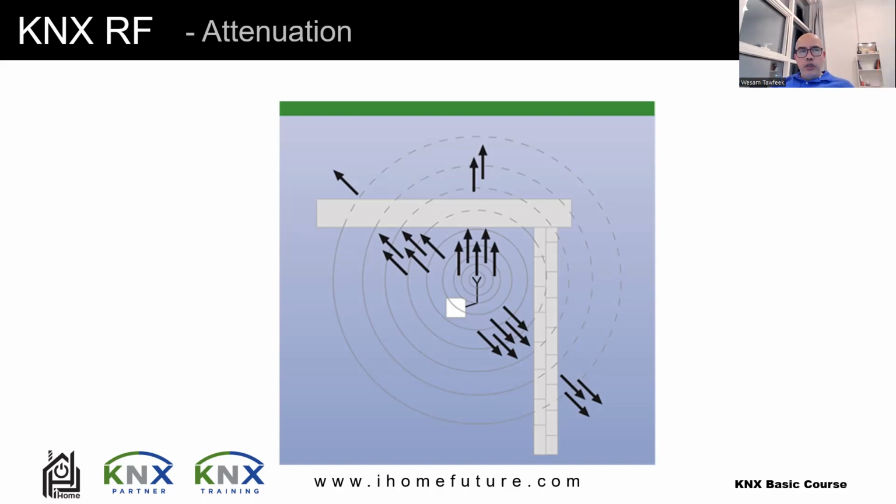One thing worth mentioning is that most of the time when we talk about wireless, the distance the wireless is covering in the papers is called a free field range. So when books or manuals say, let's say, that the RF covers 100 meters, it is what we call free field range, or an open area. Most of the time this is a theoretical range.